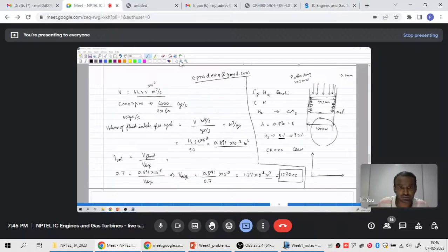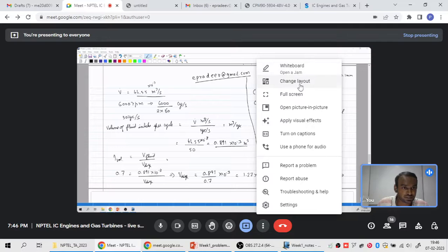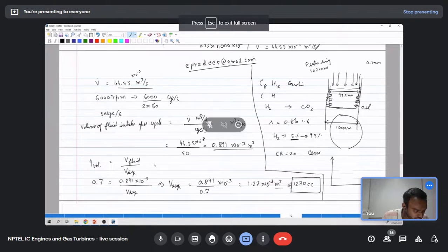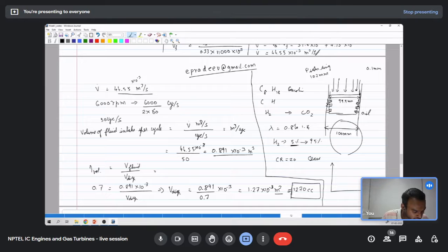Okay. Generally the diesel cycle will be like this, right? This is the pressure-volume diagram. We start from here and then compress. After compression we have constant pressure heat addition, and then expansion and then heat rejection.